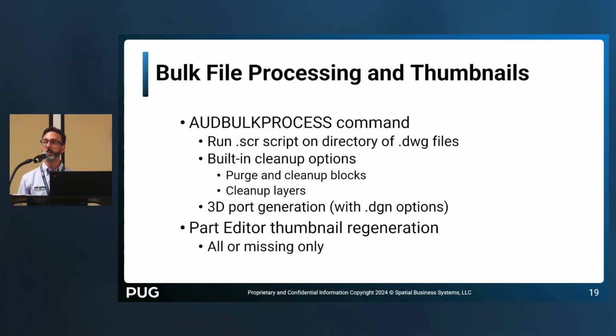It'll run it through the AC Core Console, the AutoCAD command line interface, and it will process all the DWG files in that directory. It has some built-in options that you can configure. This could be useful for pre-configuring something that does a general purge and cleanup. It can clean up layers, it can remove unused layers and things like that. So there are a few options that might be a little difficult to set up in a script or that would require you to write a complicated Lisp routine to do. Some of those options may be useful, but they're designed to just do general cleanup. So this is a tool that you might find useful as a utility to process your blocks to clean them up.